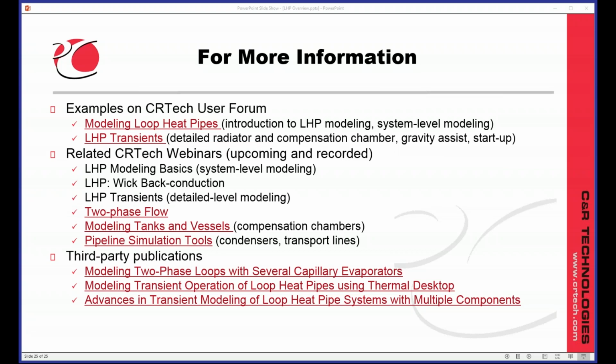An example is like propylene. Propylene would not be a very good working fluid for a room temperature heat pipe, or at least there's better fluids available, so why use propylene? But propylene is actually not a bad choice for an LHP because even though it's got a much lower heat of vaporization, it also has a really low freezing point, so it allows you to have those nice cold sections inside an LHP without worrying about freezing.